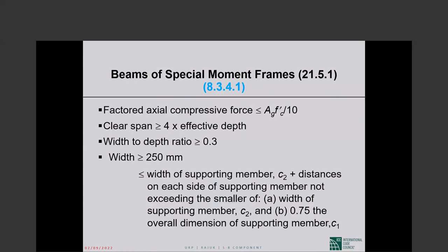The other way around, the depth of the beam has to be no more than 3.33 times the width. That doesn't give you a minimum. I do not know what to tell you. There is no minimum. If you want the beam not to stick down below the slab, you don't have a beam. You have a flat plate, and that I'm sure of.